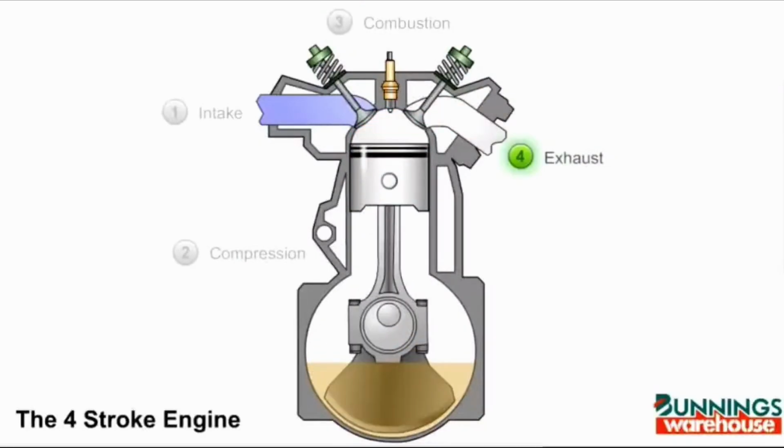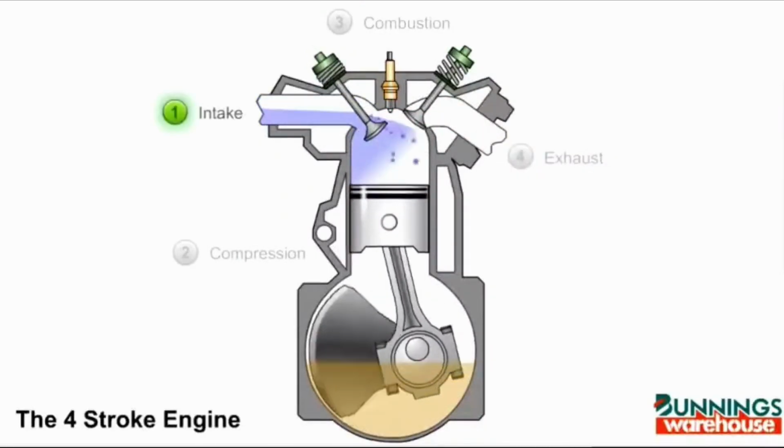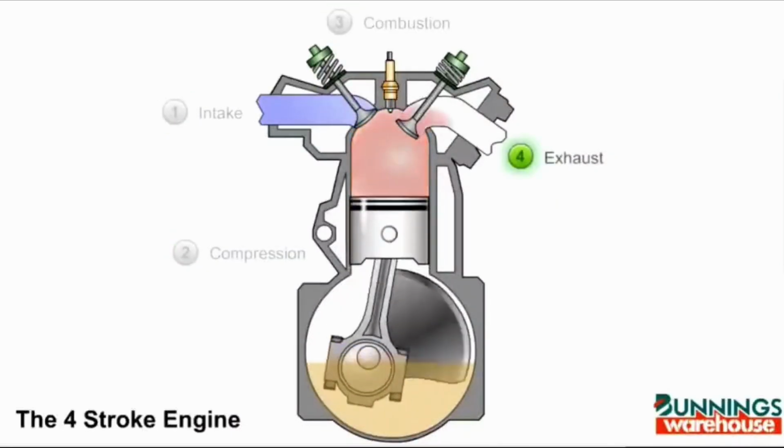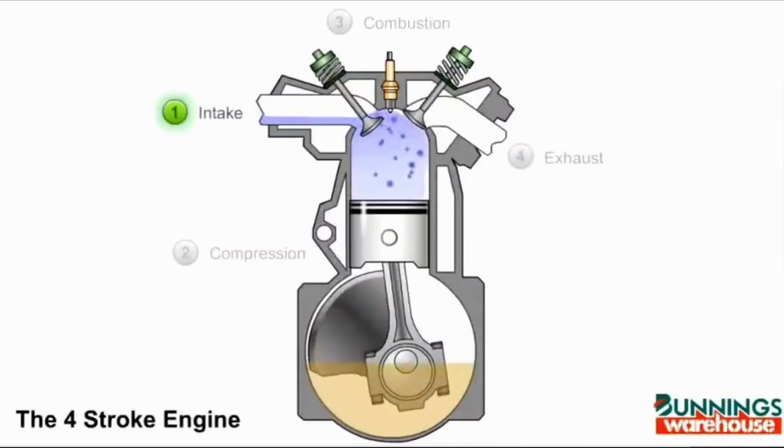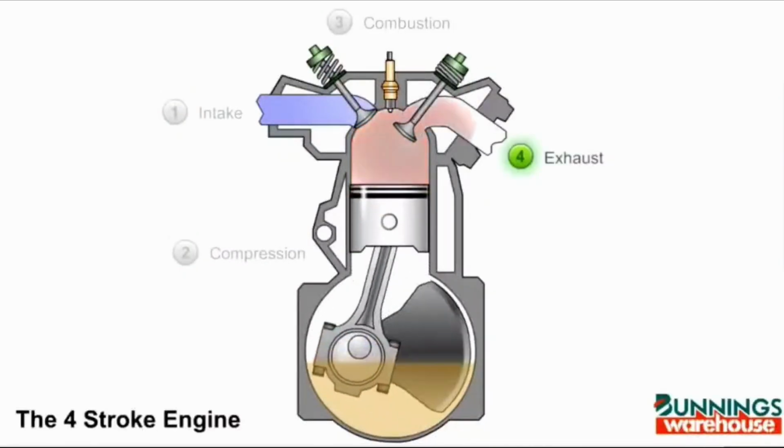In the second beat, compression, the intake valve closes and the piston moves back up. This compresses the air-fuel mixture into a smaller volume, increasing its pressure and temperature. This prepares the mixture for efficient combustion.